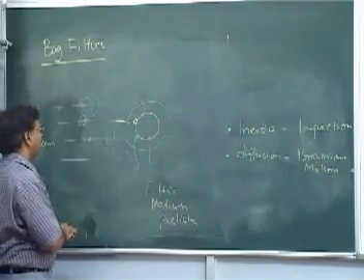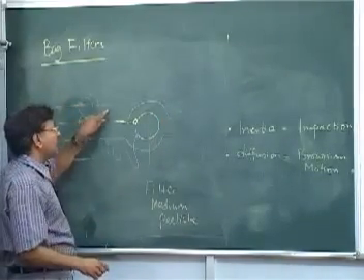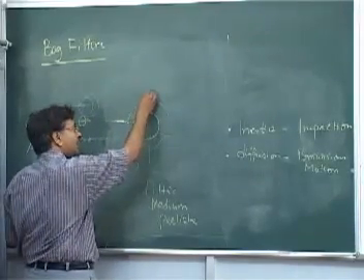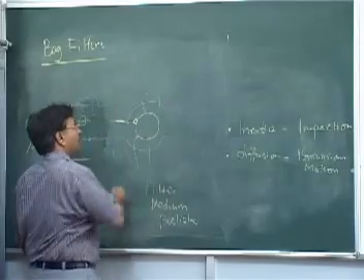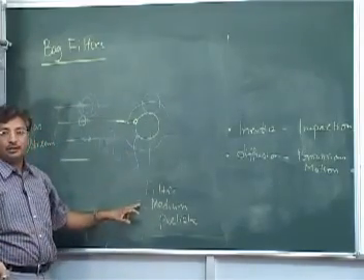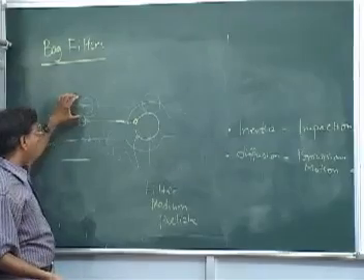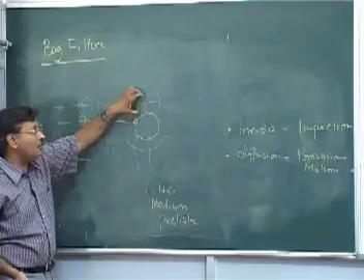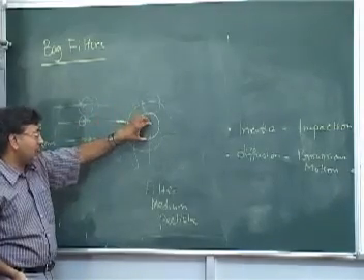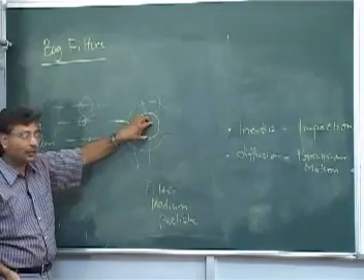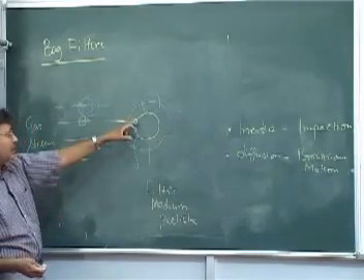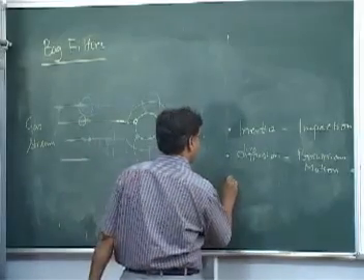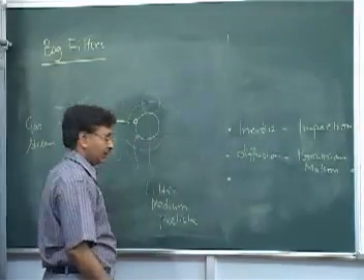Okay, but this particle, because of the low inertia, doesn't want to leave the gas stream, but you'll see the particle, which is still with the gas stream, may come in contact with the filter medium. I'm saying the inertia is low, so it will not leave the gas stream. It goes along with the gas stream, but then it might hit the filter particle, and it might just get stopped onto it. So that's what we call interception.